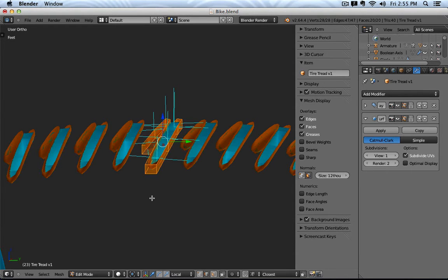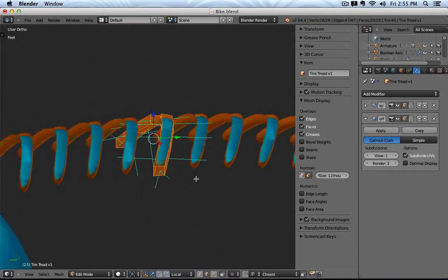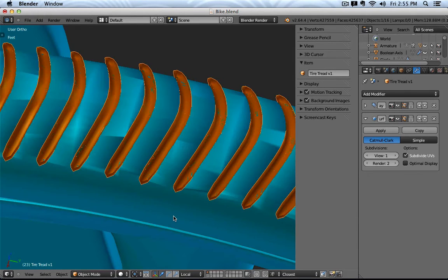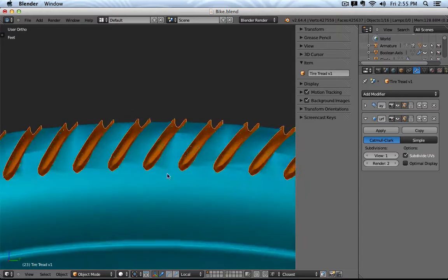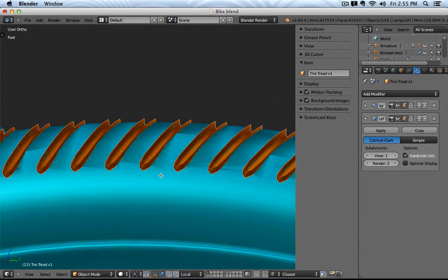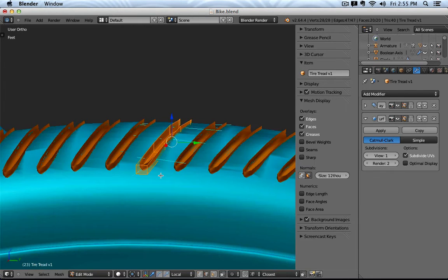That reorganizes all the different normals. Now you can see that those normals actually point outside. And if I leave edit mode, then that is fixed. So the normal direction inside the mesh when you do Boolean operations is very important.